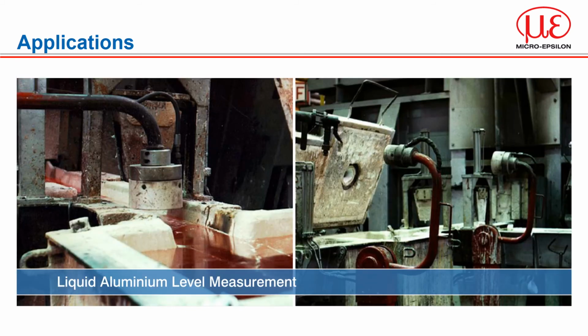Another extreme environment is to obtain a homogeneous oxide-free aluminium die-cast. The aluminium level in the open mould must be kept constant to within 1 mm. A constant level is achieved by controlling tilting of the furnace. The current level is measured and monitored from above with air-cooled eddy current sensors. A temperature stable output signal and the high operating temperature of the eddy current sensors are particularly significant in this measurement. A similar principle is used for solder wave height control in the electronics industry.